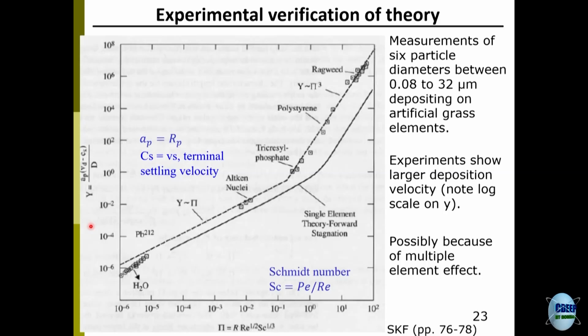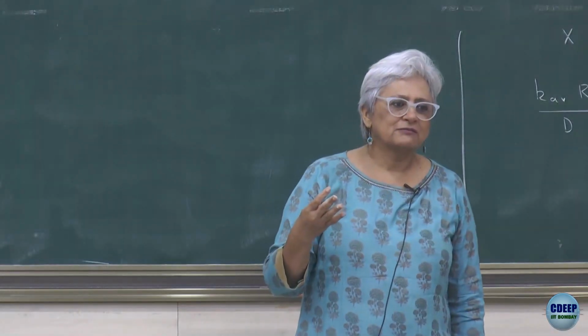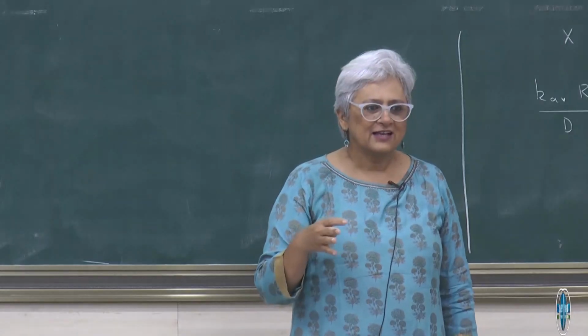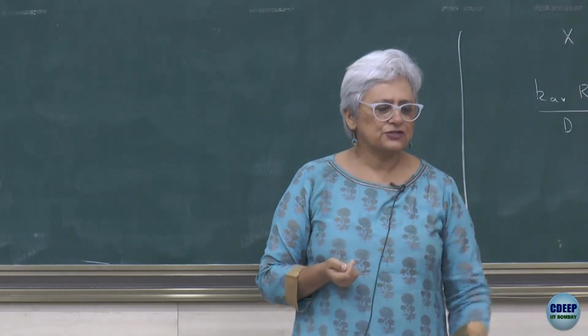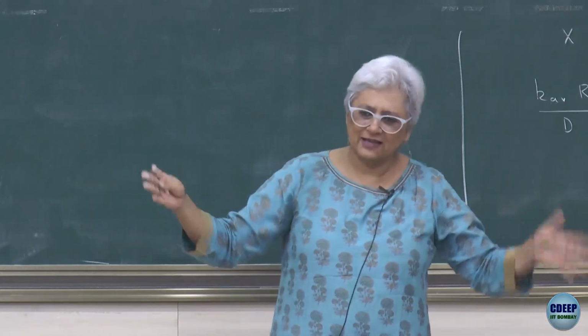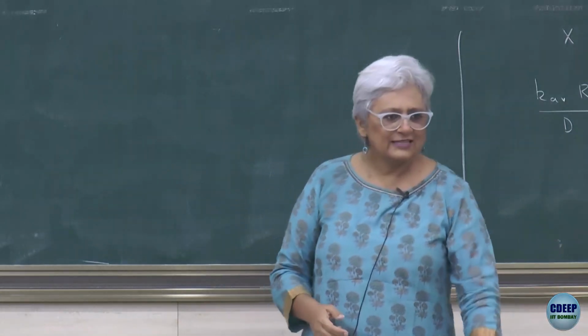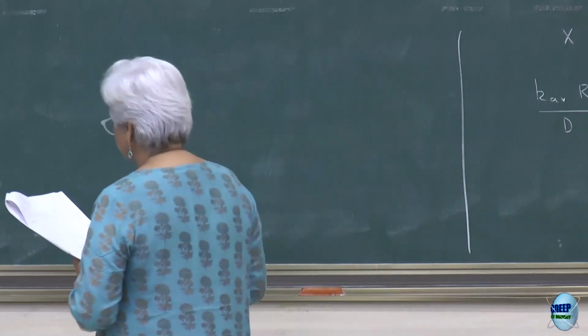So, wind tunnel experiments in which they simply used to put, like your artificial grass kind of material at the bottom and flow. I've actually been around such experiments being done in our lab during my PhD days by somebody else. And you flow the fluid through it, and you measure the particle concentrations upwind of it and downwind, at the start of the experiment and at the end of the experiment, and you end up with the removal efficiency.